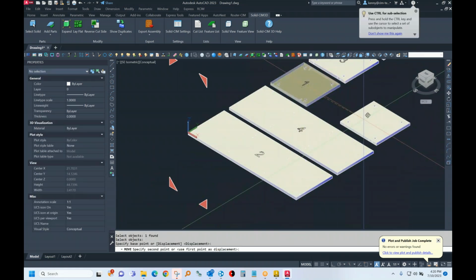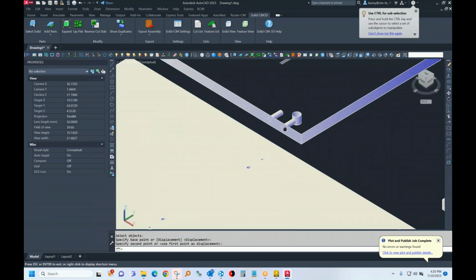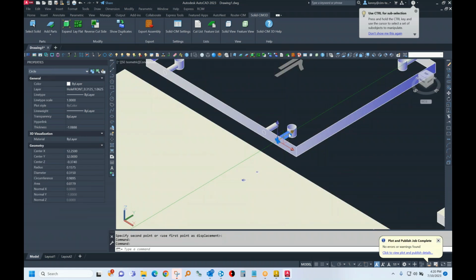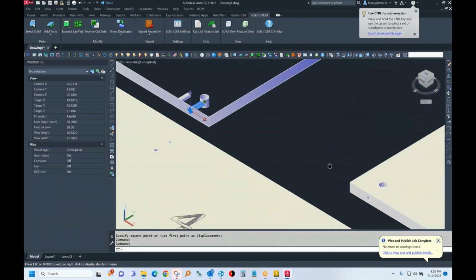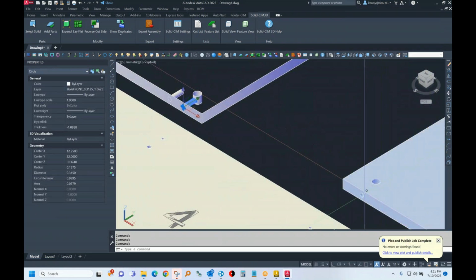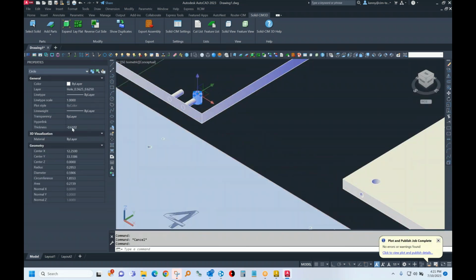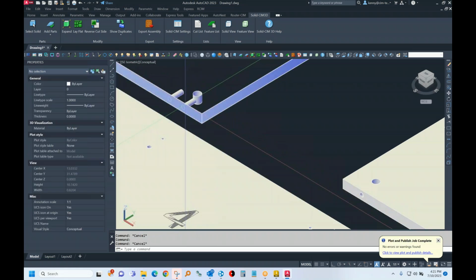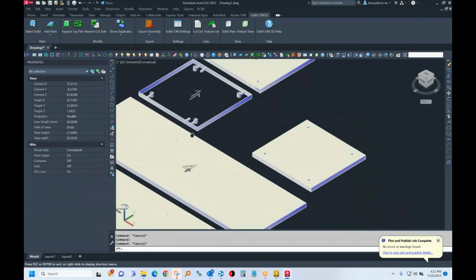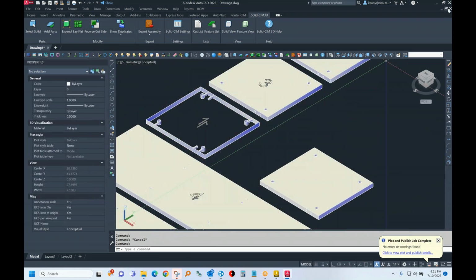So if we move this solid out of the way here, you could see we've got your, oh geez, I forget what those things are called here. It found a hole on the front and on the top. And you see it's got the depth. That's how thick you drew it. So we get the full 6-sided recognition. A cam lock, that's what these are called. So it recognizes those, and you get the geometry for both operations, the top and the side operation.